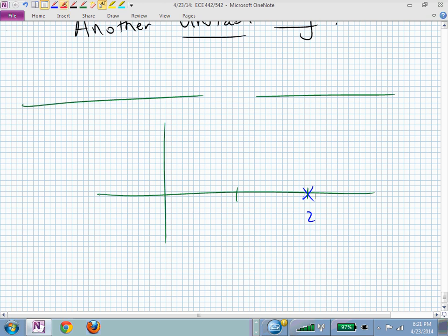Well, if we do a PID controller, we're forced there, but what if I don't force the zeros to be on top of each other? Real and equal. Maybe I let them be real but unequal. If that's the case, where would I locate these zeros?